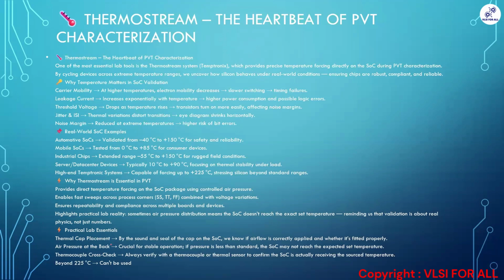And we have to see whether that SOC is getting the set temperature. For example, if we set 50 degrees and we have a doubt that we are not getting 50 degrees, to ensure that correctness, we will use a thermocouple or any temperature sensor to see whether we are getting the correct temperature as we set it on the Thermostream.